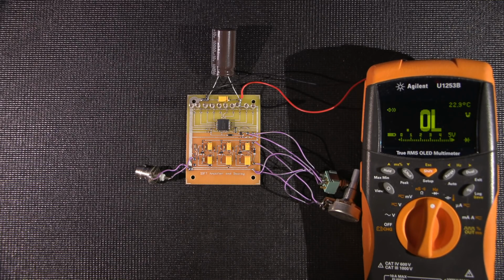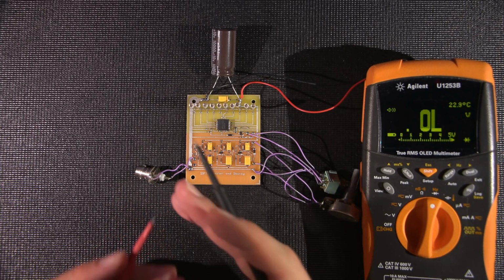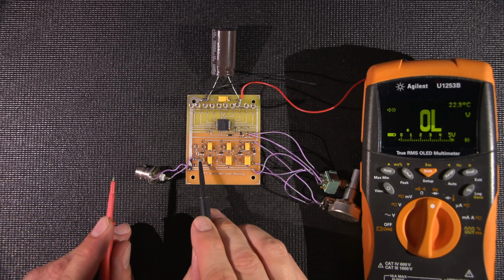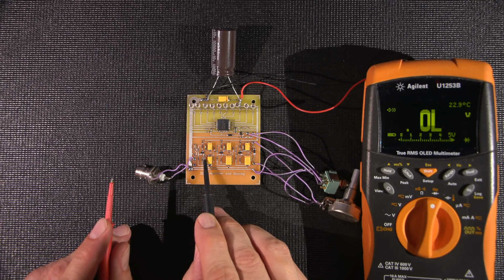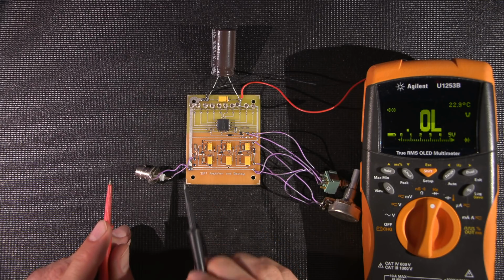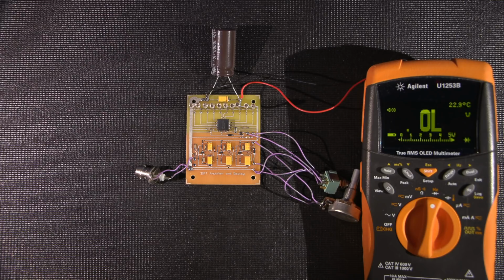It's hard to get both devices in focus at the same time, so I'll switch back and forth. So we know already the pinout because it's very standard. So we know that this is the base, this is the collector, and this is the emitter right here on this little transistor. So if we wanted to check for an NPN transistor, right? N being the collector, P being the base, and N being the emitter.